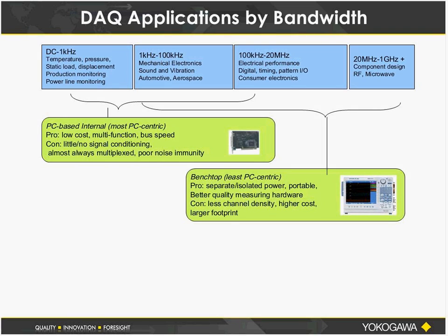Those are quite common. Some people consider data acquisition to apply to higher speed bandwidths as well, kilohertz to megahertz type of application. And again, no matter what type of category you're looking at, the noise is going to be relevant. Certain types of noise will apply to different speeds a little bit more obviously.